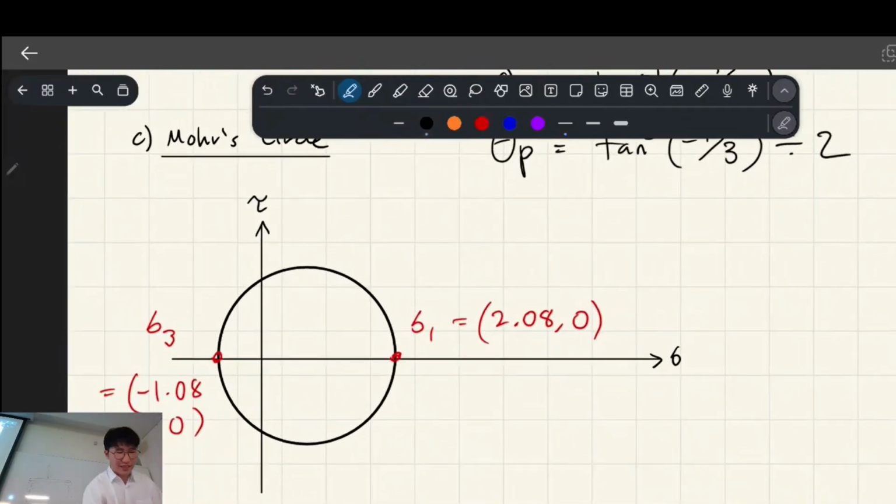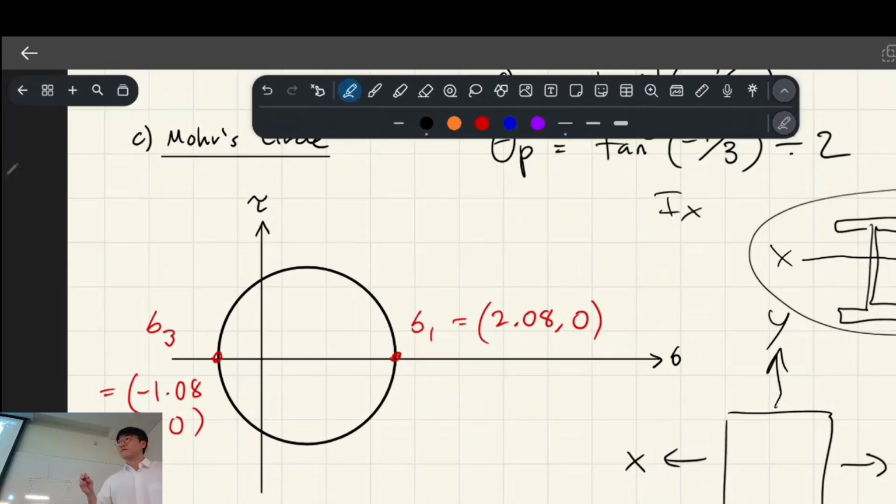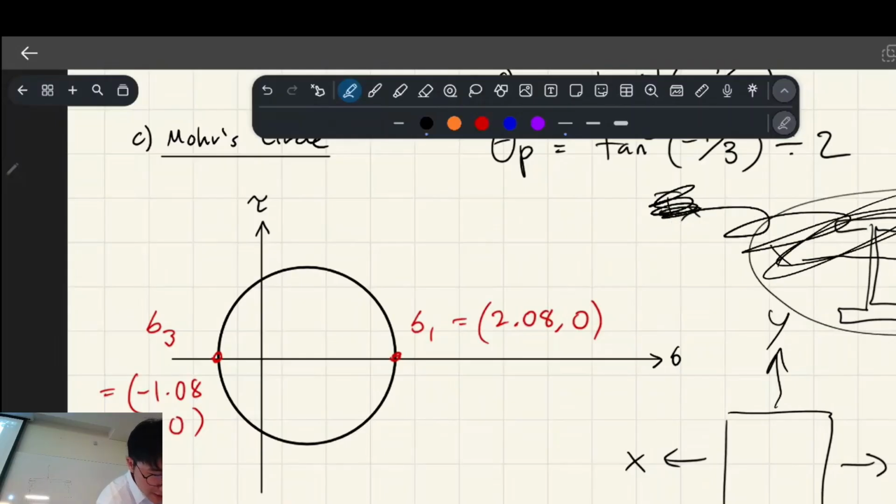By the way, just because we're shown a stress element and we're told that this is x and this is y, doesn't necessarily mean it's the principal stress. Do you know what I mean? Because before we were looking at I-beams, and an I-beam bending about its x axis is the strongest direction, right? And so therefore the Ix was actually the principal plane. That's not the case necessarily.